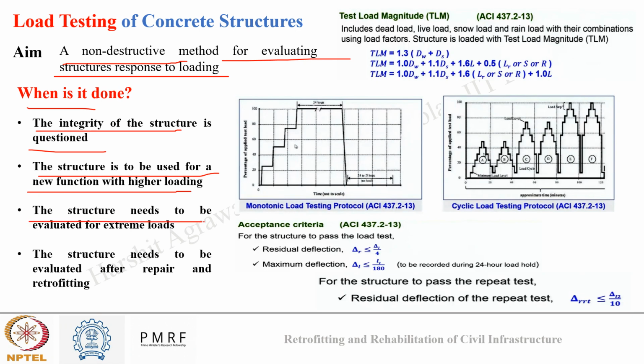Third, when the structure needs to be evaluated for extreme loads, so suppose we have designed the structure and we need to check whether the structure can take extreme loads or not, then we conduct load testing. And fourth, when the structure needs to be evaluated after repair or retrofitting. So suppose the structure has undergone repair and retrofitting, and now we want to estimate how good the repair was, or whether my structure is strengthened enough to take the load again, so I can do the load testing.